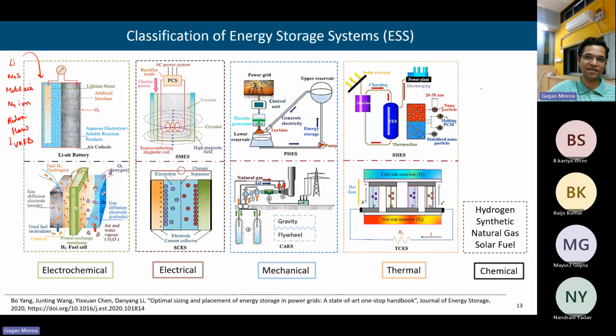In Maharashtra also you will find the upper reservoir is a natural reservoir. The lower is a man-made reservoir. So the operation of the pumped hydro is limited by the capacity of the lower reservoir. And its operation is also very dynamic in monsoon. If you see, this upper reservoir is already filled, and then we cannot pump water from the lower reservoir to the upper reservoir. In that case, we can only generate.